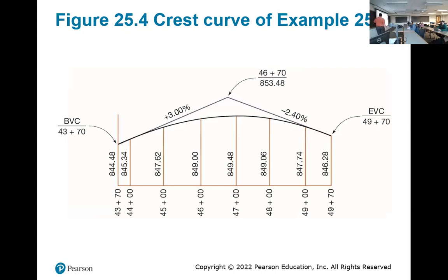So in surveying, if you're given that your beginning of vertical curve is here, you can calculate 4370 to 4970. Everybody sees how this is a 600-foot vertical curve. The PI, it doesn't matter if this slope is different than this slope. The PVI is going to be halfway in between, no matter what. So if you add 300 feet to this, you're at 46 plus.